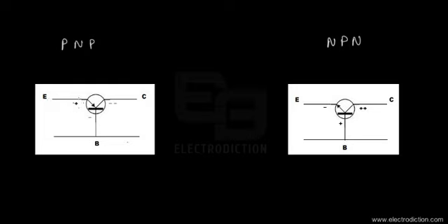So we have a positive symbol on the emitter, negative symbol on the base. Okay. While in case of biasing the collector, the junction between the collector and the base, that's JC, we are putting a more negative polarity voltage on the collector with respect to the base terminal, so that this junction is, of course, highly reverse biased.